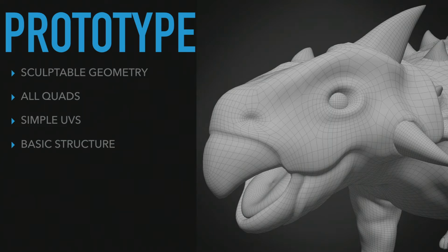Here's another great example of an area that would get optimized in production: the tongue. Look how many polygons are on that tongue. That's a lot, like a 4,000 polygon tongue. In the final production model, I think that got zipped down to like 100 quads. So that's where the final is different from the prototype. But now at least we have an underlying foundation that we can build and change that makes sense inside of our quad polygon workflow.